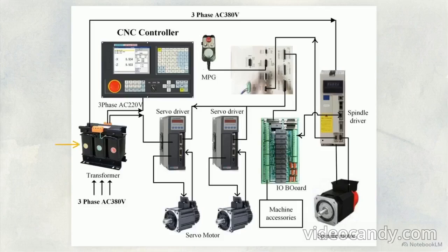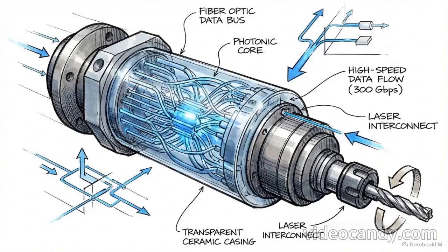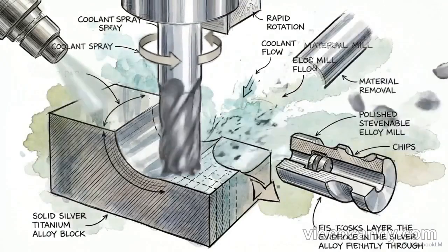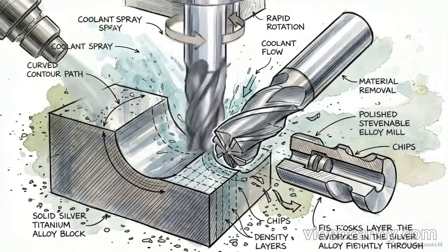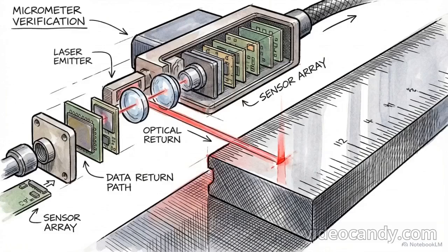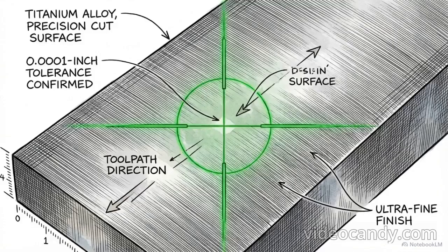When we map all of these disparate components together, the cohesive architecture of the machine is revealed. This system wiring schematic traces the complete life cycle of a single toolpath command. You can follow the routing of the high-voltage, three-phase AC power from the transformer up to the drivers, supplying the brute electrical force. Running directly alongside it is a complex web of low-voltage command data flowing outward from the MCU to direct exactly how and when that brute force is applied. Stripped of its steel casing, a CNC machine is effectively a high-speed data network designed to perfectly manipulate heavy industrial hardware. All of that intricate network complexity exists for one single purpose: controlling the physical reality of cutting metal.